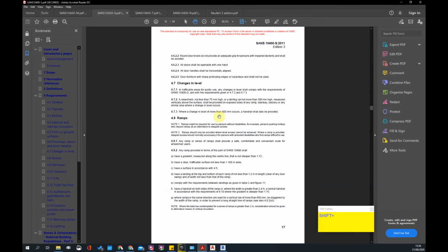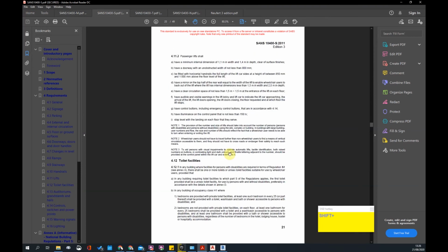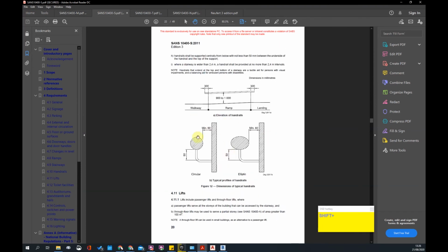So here, for example, let's go to the hand railings. How your hand railings work, the height of the hand railings. Generally we have a meter hand railing. If you're going to put a railing against a wall for a ramp, we'll make that 900. For an older person to grab onto it, it's better. For a stair, it's not so much a case of you holding onto the hand railing so that you don't fall off the stair.